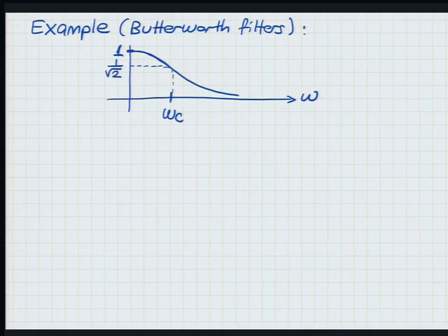There are several filter design methods out there for analog systems. They include Chebyshev, and there are all kinds of names. But usually, either in the pass band, the low frequency region, or in the stop band, the high frequency region, those designs will have ripples. Butterworth is good because it's smooth all over. It's monotonically decreasing. You don't get these funny ripples, okay? So that's the idea of the Butterworth filter.